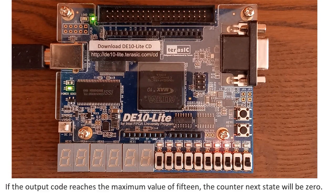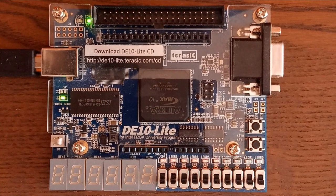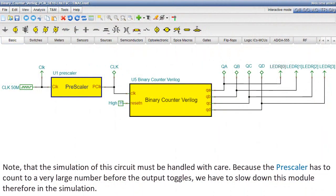If the output code reaches the maximum value of 15, the counter next state will be 0. Note that the simulation of this circuit must be handled with care, because the prescaler has to count to a very large number. Before the output toggles, we have to slow down this module therefore in the simulation.